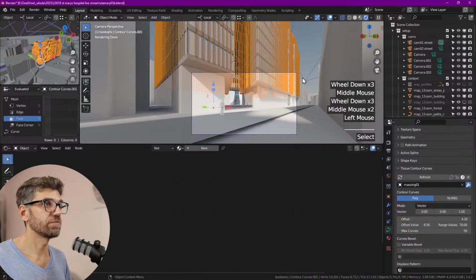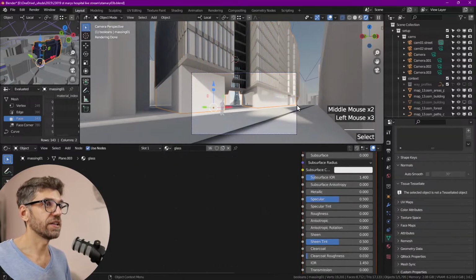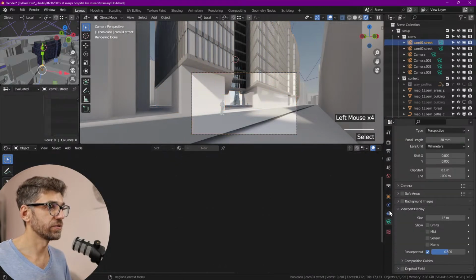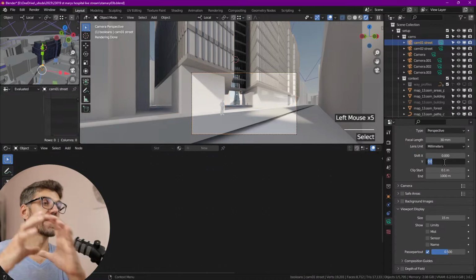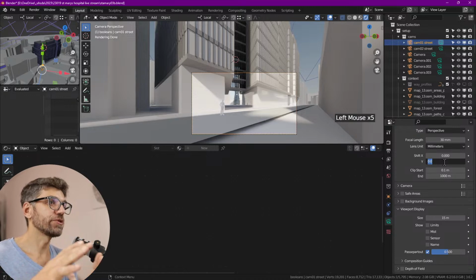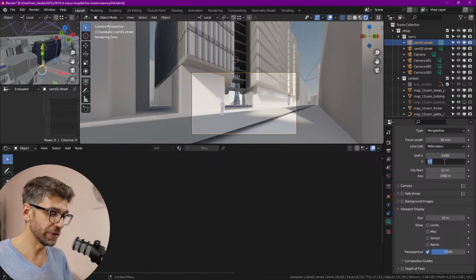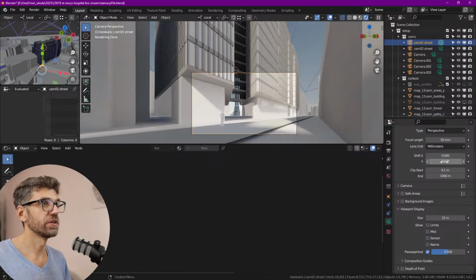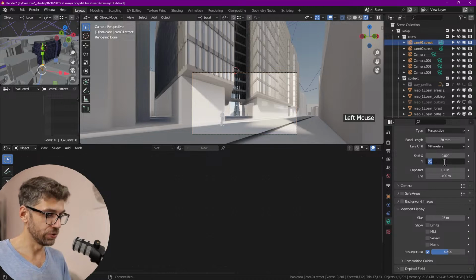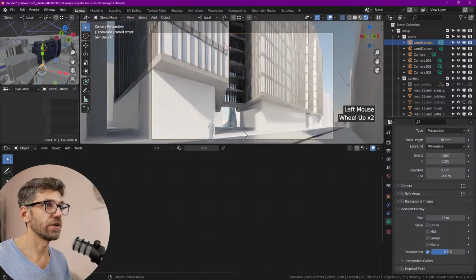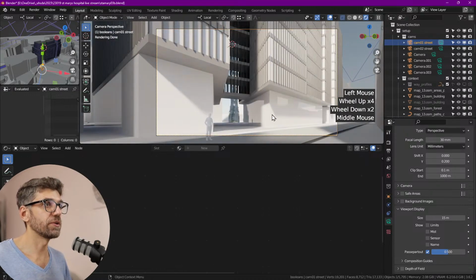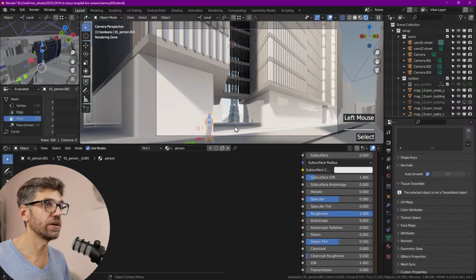Okay, so I'm going to put this camera slightly higher, and we can drag the Y shift, so the viewpoint stays exactly in the same position, but it just shifts the perspective. It's like lens shift, which is typically used for architecture. So if we go to something like 0.1, or let's try something like 0.2. There you go. Now we see a bit more of the building, and we can start to understand what's going on in there.